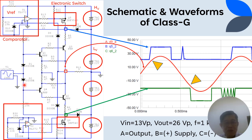Here we set the input with a sine wave of 26 volts peak to peak, or we can say 13 volts peak, with a 1 kilohertz frequency. After amplifying with a gain equal to 2, the output signal has 52 volts peak to peak, or 26 volts peak, as shown in the waveform in red. So we can see it here in the red.